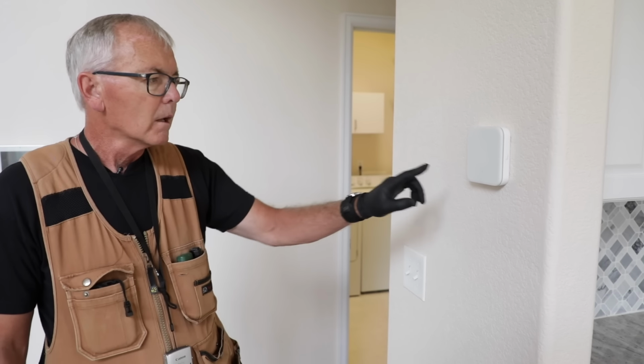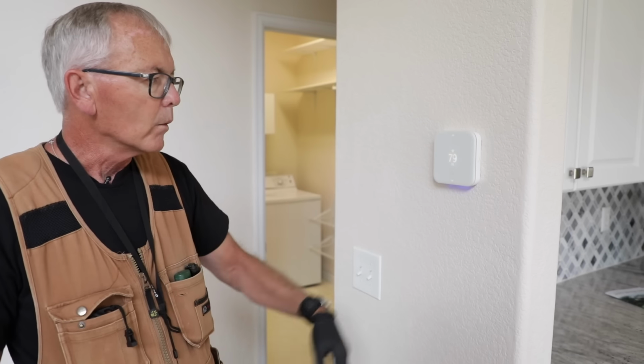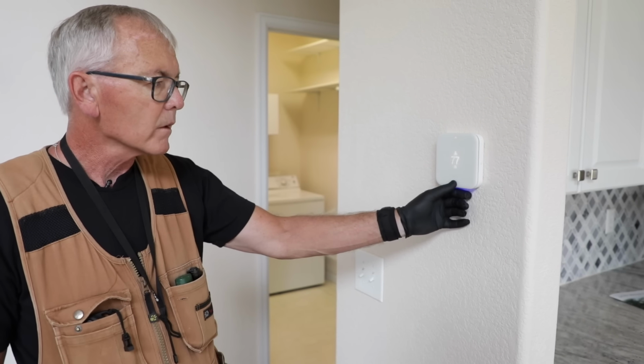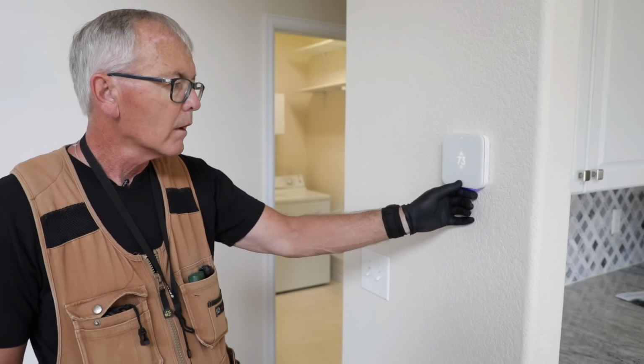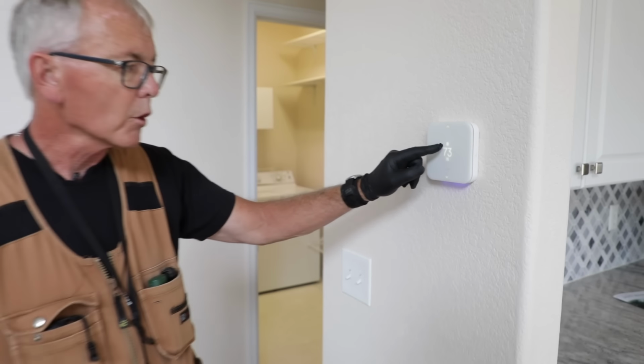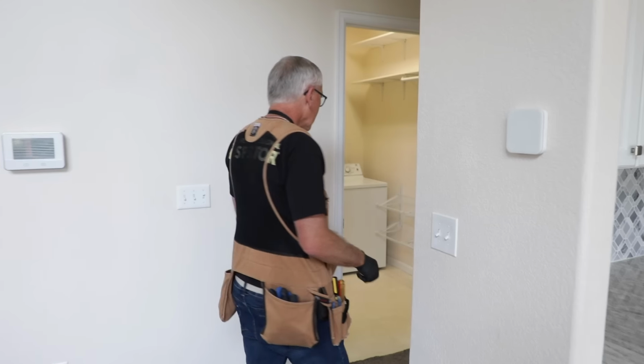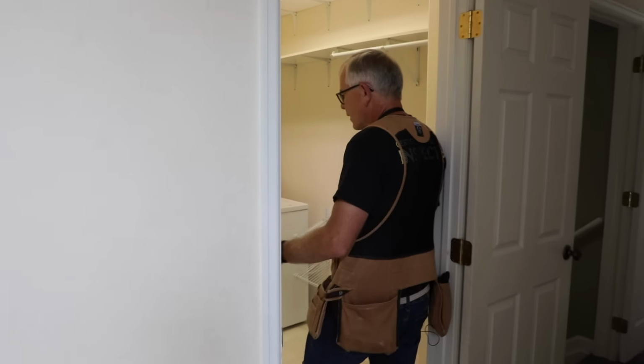We're moving on to 3.5, cooling. The inspector shall describe the cooling method and the normal operating controls. So again, we're here at the thermostat. We are going to try to engage the AC. And I can see here that it's showing that it's been engaged. We'll go down again so you can see it. You see the change right there. So let's go outside and take a look at that condenser.